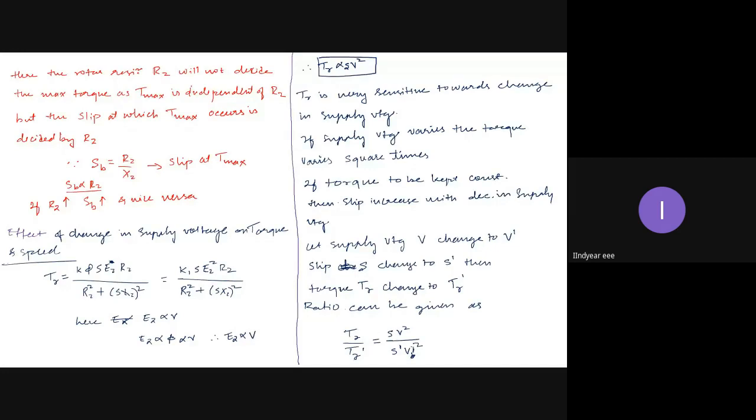Did you observe this point? If not observed, anytime when you see the elevator, observe this point. The elevator will always run at a constant speed, whether there is one person, two persons or 25 people on the elevator steps. As the people increase on the elevator, the load torque requirement will increase and speed will decrease.